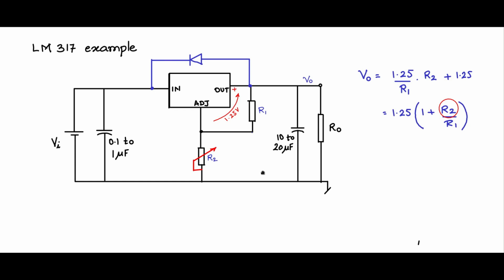Another important component we can add is a capacitance here, 10 microfarad. This will act like a filter and stabilize the potential here. Once it stabilizes the potential here, output regulation is much better. However, you will see that when you switch off, there is no discharge path for this 10 microfarad capacitance. It has to be through R2, or through R1 and the output capacitor or the input capacitor. This can be a long time constant.